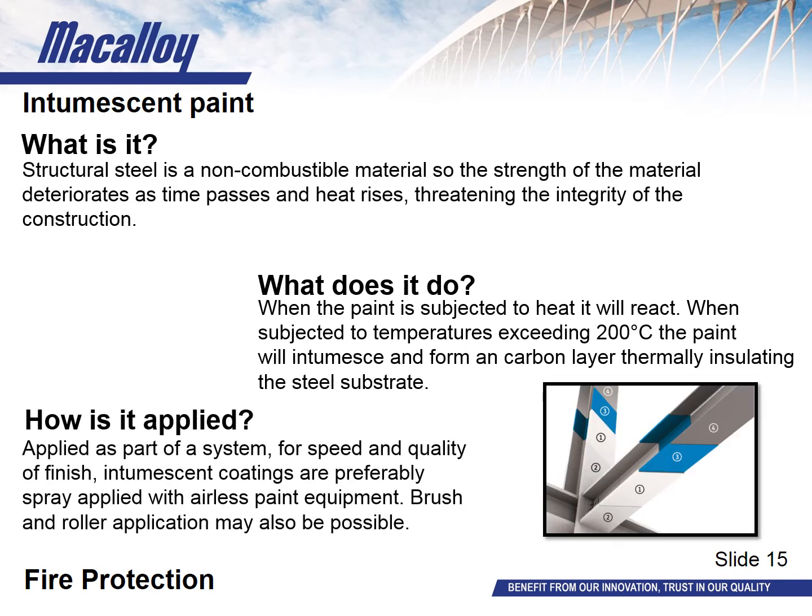So intumescent paints are always made up as part of a system. For steelworks, the system includes an anti-corrosive primer and a top coat. So the primer is used for assuring adhesion to the substrate, anti-corrosion protection and stickability of the intumescent char formed during the fire exposure. While the scope of the top coat is really to provide aesthetic function whilst also adding additional corrosion protection and weathering resistance to the end use conditions.